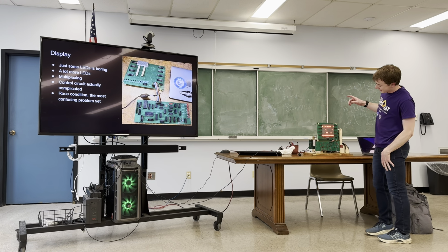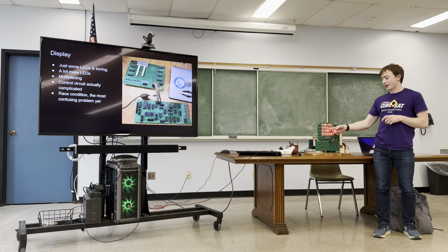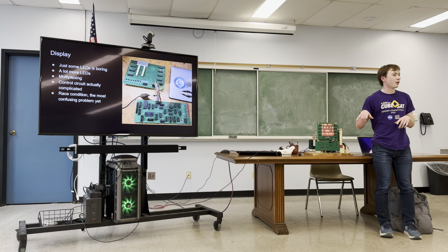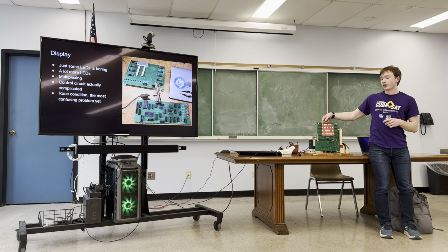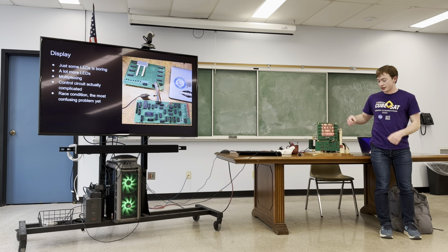Alright, so what it does is it doesn't actually power all the LEDs on there at once, because there's 32 by 32 of them, so you need 1024 outputs from a bunch of probably 8-bit latches, and that would make the wiring on the board really complicated, and it would just be a pain to design.